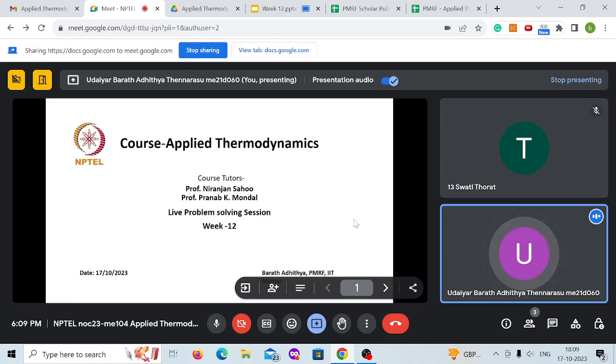So these are the major different types of compressors available, and the difference between them is that a reciprocating compressor is not continuous. You have a gap between each cycle: there's an intake, then compression, and then exhaust, and then it should take an intake again. So it's not continuous if you compare it to centrifugal. There is a distinct difference there.